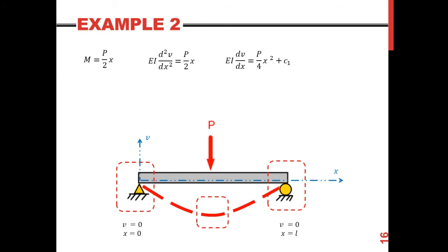Now I talked about the deflection, as the deflection is going to be 0 here at both ends. But that's the deflection. What I have here is the slope, dv over dx. And how would I compute the boundary condition if I only have the deflection? Simply, for a simply supported beam, exactly at the midspan, I also have the slope. If you just draw a straight line here, you're going to find that the slope is 0 here,